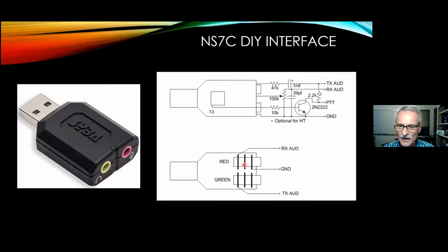It's got those two big connectors on there, and I don't even take those connectors off. The first couple times I messed around with one of these, I tried taking the connectors off, and even with my hot air soldering station, I loosened up the land traces on the board. So just leave the connectors on.